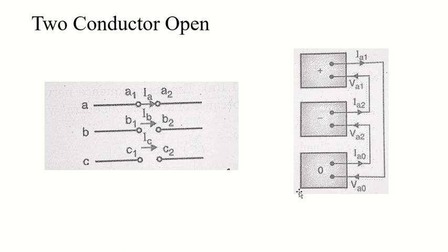In that you can see Ia1, Ia2 and Ia0. Ia1 is going from here and connecting at Va0. Ia2 is moving from here and connecting at Va2, and Ia0 moving from here and connecting to Va2. So it indicates that the sequence networks for this fault are connected in series, right? So that's the wrap for the sixth chapter.